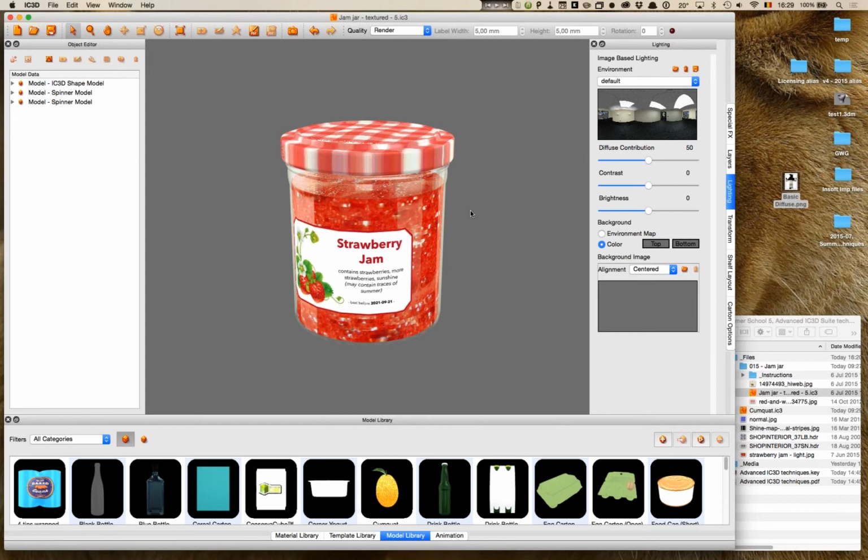What I can do is press the S key, and I can't show you that I'm doing that, but I'm simply pressing the S key, S from Sarah, on the keyboard, and then I'm going to take the mouse, click on the background, and simply drag that background. And as I move the mouse with the S key pressed, you can see that I'm actually rotating that lighting